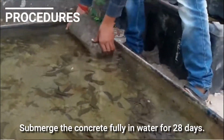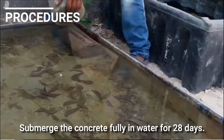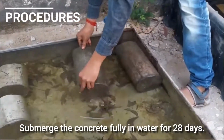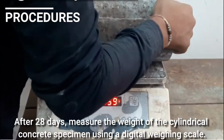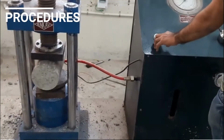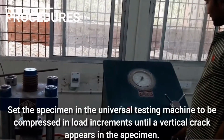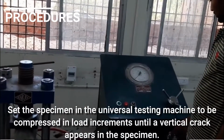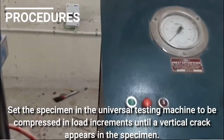Then, submerge the molded concrete in water for 28 days. After 28 days, measure the weight of the cylindrical concrete specimen using a digital weighing scale. Lastly, set the specimen in the universal testing machine to be compressed in load increments until a vertical crack appears in the specimen.